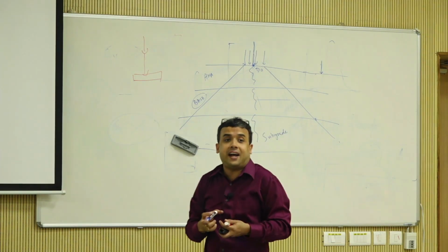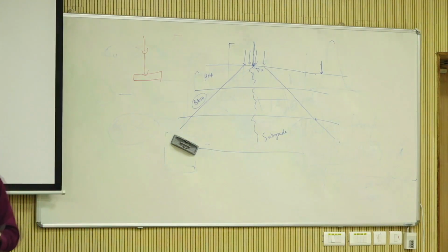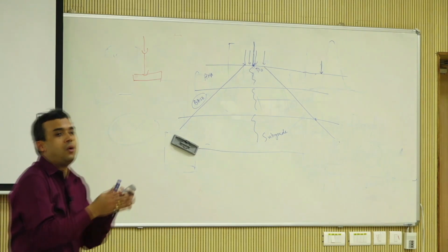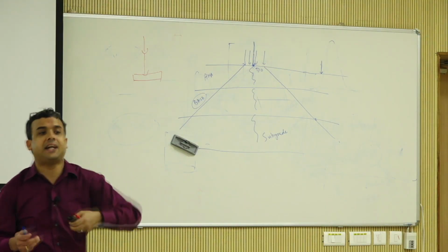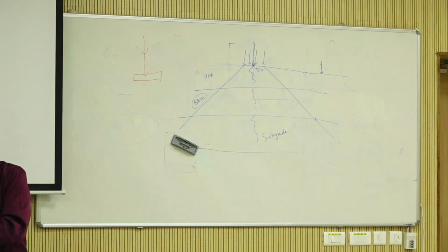You use that concept when you are trying to calculate your modulus values for layers and stuff like that, which is called back calculation. We'll get into that in a second, right? The whole idea is as you move away from the load application point, the layer that affects the proper deflection or the behavior is going down, down, down, down, down.